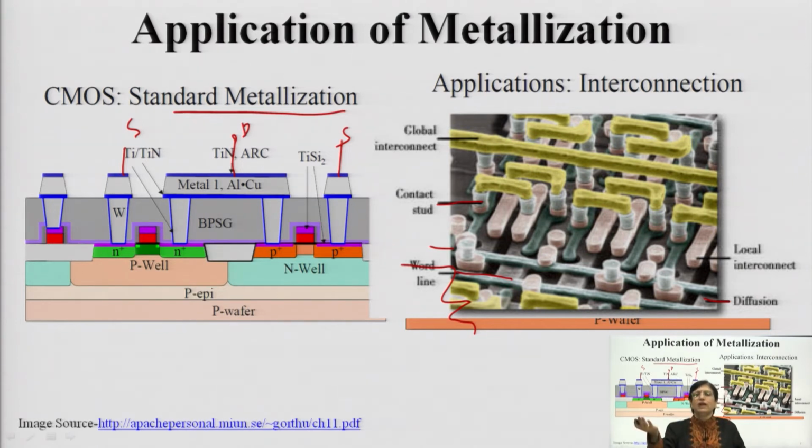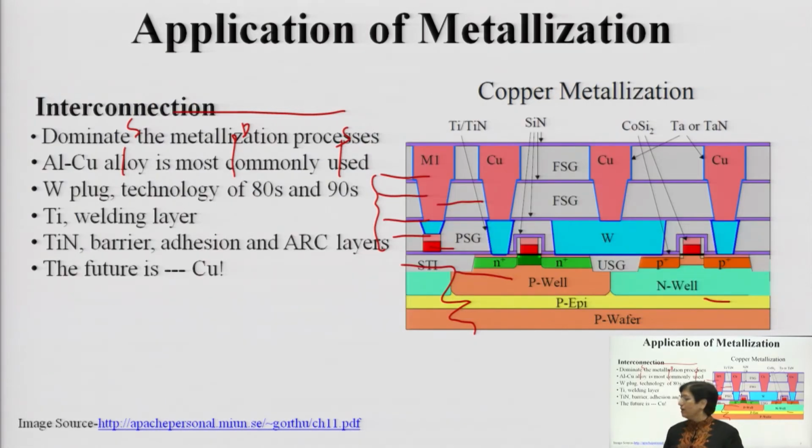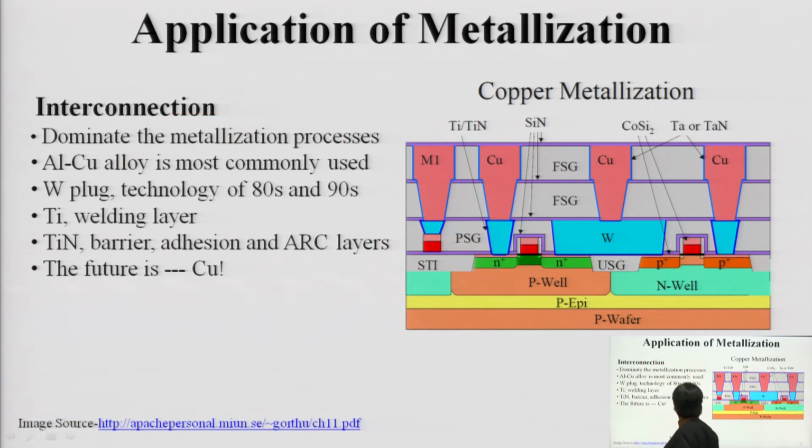At one level you will have all drains connected, at another level you will have some other nodes connected. So, these are the window openings through which the metal contacts are brought up, and as many as 7 to 20 layers are there for the metallization, which make a complex circuit function. All the complex interconnects will have their complexity resolved by incorporating them in a multi-layer structure, and that is how you attain multi-level metallization and carry out this particular job. So, this is one of the features through which multi-layer metallization is being done.